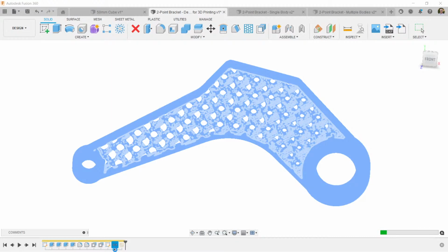So the next question becomes, okay, well, what can you do with this final mesh? Well, of course, 3D printing is the obvious answer, right? Like that's why most people are making lattice structures. It is very difficult to machine lattice structures, but it could potentially be possible depending on that structure. And things like traditional manufacturing processes like injection molding or casting, those could be difficult to, if not potentially impossible, depending on the lattice structure. Latticing is really optimized for 3D printing.